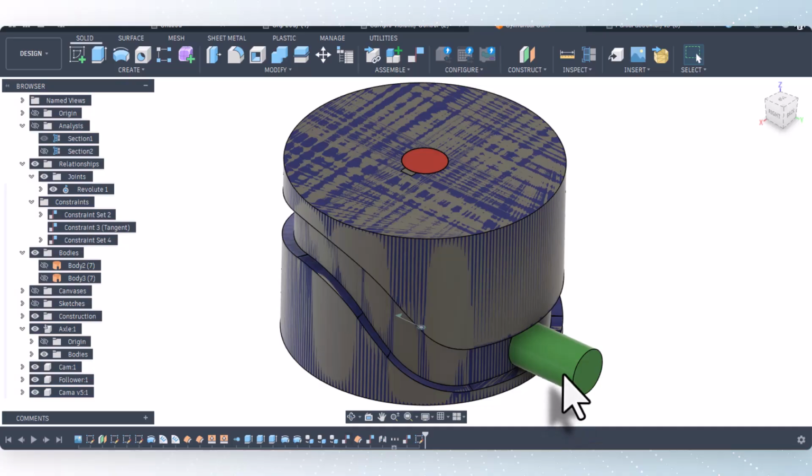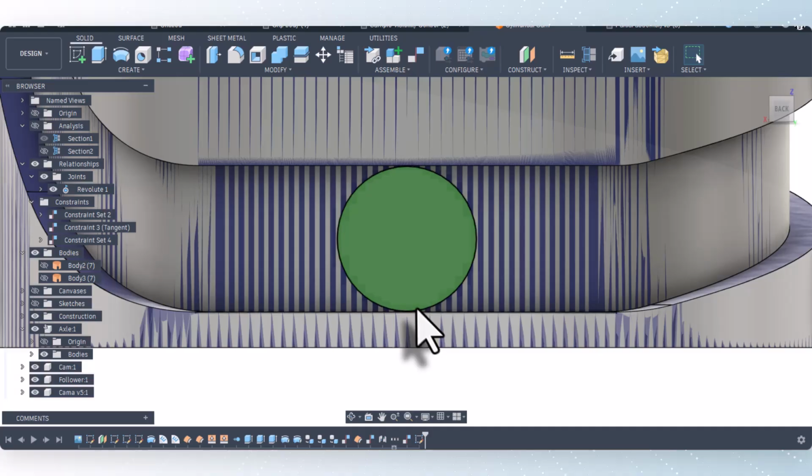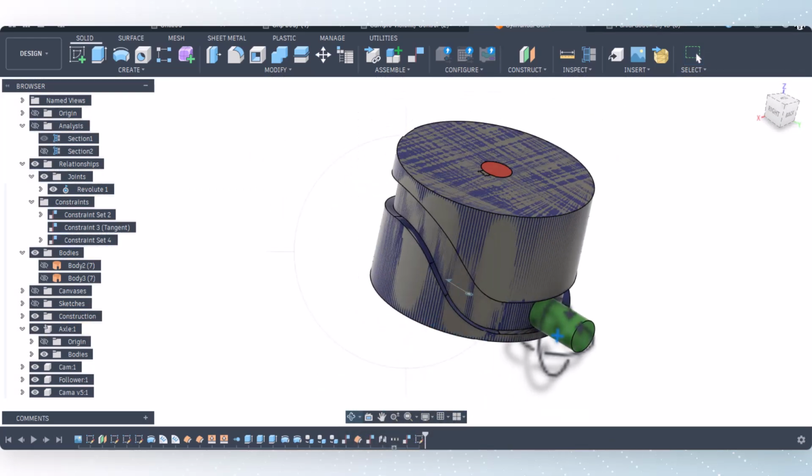If you think about the geometry, it's actually as a cylinder rotates around in an end mill, or the part rotates as the end mill translates to cut that geometry. So the tangent point between the cutter and the face of the slot is continuously variable. At this position, it's at the 12 o'clock and 6 o'clock position, but as it goes around, it will move up here or move along here, depending on which direction you're going. But the tangent point is continuously variable as we start to go up along this. And plus, we are going towards the center of this.